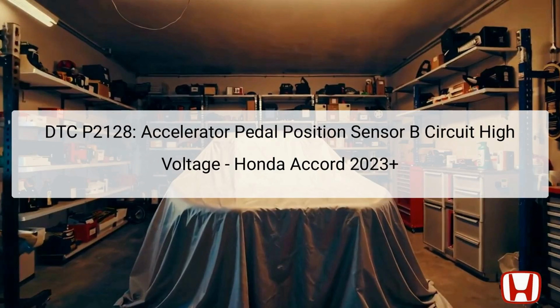The APP sensor is integrated with the accelerator pedal module, which is positioned in the vehicle's engine compartment. Its primary role is to communicate the position of the accelerator pedal to the PCM, influencing throttle response and power delivery. When this circuit faults, it can lead to performance issues that could compromise vehicle safety and efficiency. Understanding this code is crucial for accurate diagnosis and effective repair.